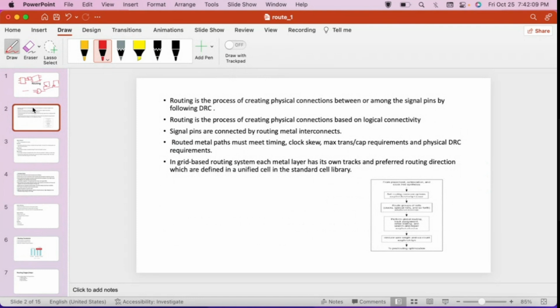The next is clock routing. You see it during the building of the clock, which takes place in the CTS stage. Once standard cells have been placed, the flops get routed using clock routing through the CTS engine. The next step is called routing, where the routing is called signal routing. It is after CTS and can simply be called routing. Hope you understand that.